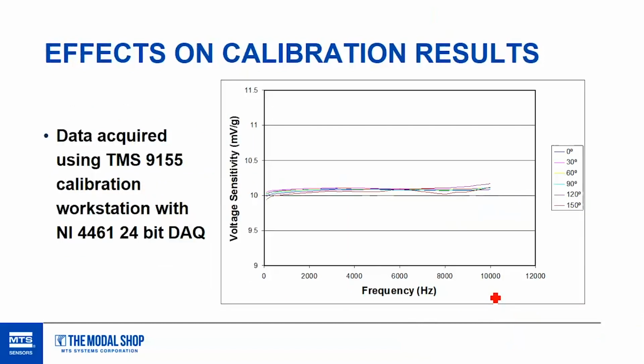So exact same test, exact same rotation, this is the result. A very consistent sensitivity value you get on your sensor that is really kind of independent of that rocking mode because it doesn't exist, right? No rocking, which means no transverse output in that range.